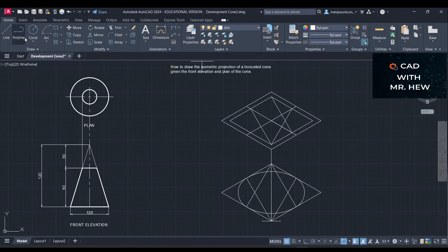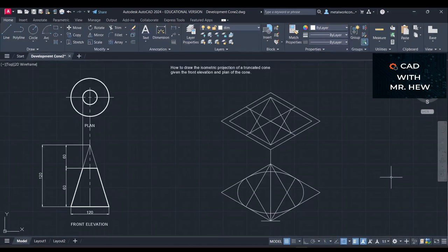All right, so we're going to repeat the process. We need a 60-degree line from here going down. What would the angle be? 60 degrees to the horizontal, coming down. I think it would be 210. Good. Enter. All right, so here we have the construction for the circle, the smaller circle at the top.